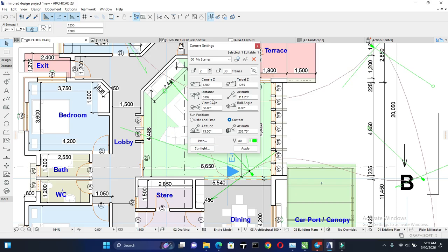So it's almost looking straight. If you want it to look up, you can change this aiming to 1.5, 1.8, 2.1, and the rest. If you want it to look to the ceiling, you know what to do. Increase it. The more you increase it, the more it looks up. The more you reduce it, the more it looks down, based on where your camera position is. So that's basically how to tweak your camera. There's no long deal about it.